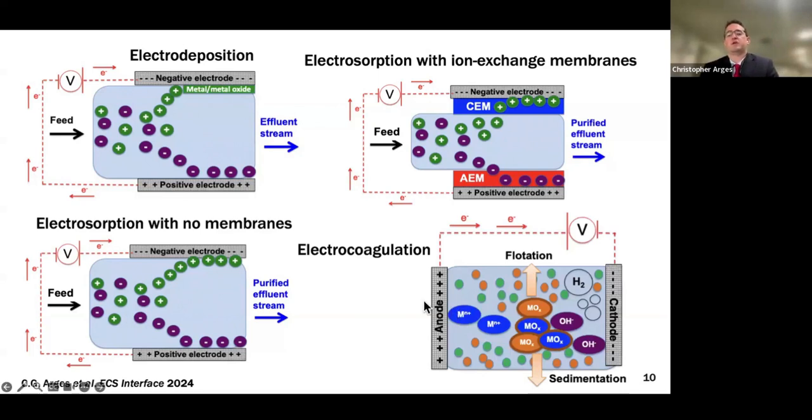There's also electrocoagulation, another method, and there are various embodiments of this method, but you can basically oxidize a metal. This metal could chelate with a species to precipitate it. Then you could have flotation or sedimentation to collect it, or you do water reduction at the cathode, generate hydroxide. This could react with different metal ions within the solution, make metal oxides, and again, you can centrifuge as a way of separating out the different metal ion species collected from the solution mixture.